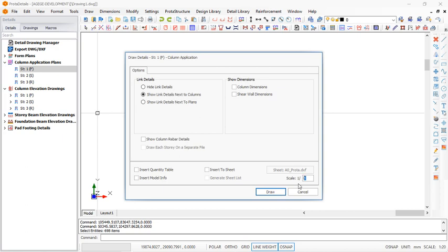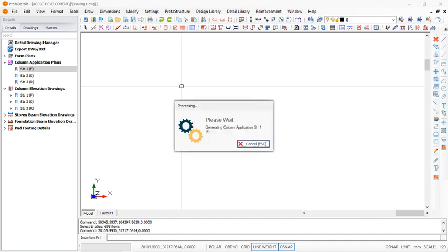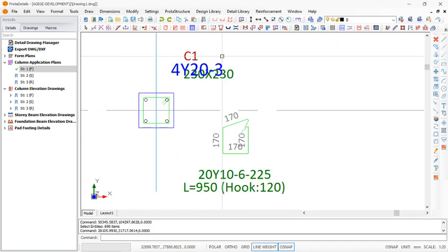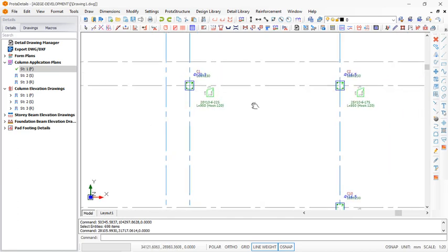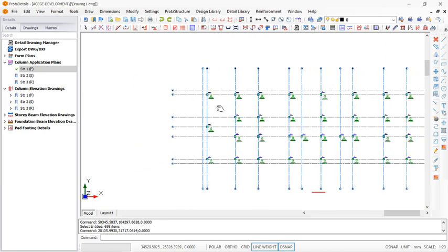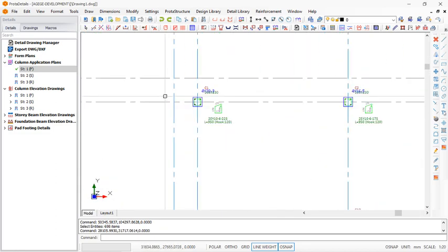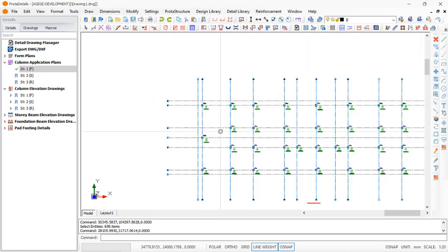The reason is that if I use 1:20, the drawing will be very tiny, which will not be visible enough for anyone to make meaningful deductions from it. So that's why 1:20 would not work in this case.